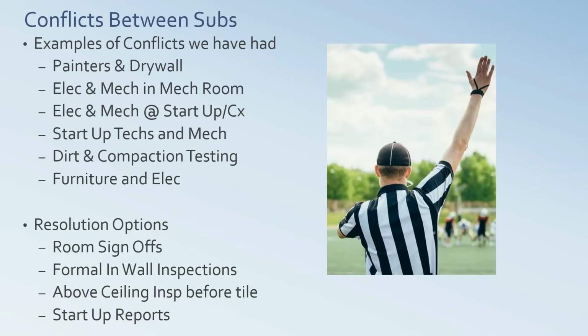Why do they need to be there? It's explaining why they need to be there. Startup technicians and mechanical, again, why they need to be there, getting the reports in a timely fashion. And sometimes little things that come up during startup for electrical, mechanical, and the startup techs can be resolved right there if you have all the players right there. For 30 minutes when they're starting the equipment up, if they're right there and there's one wire that didn't get landed or one thing that needs to be tweaked. Motors running backwards. Oh my gosh, how many motors have we found backwards?